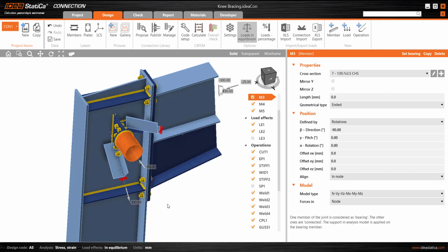There is an invisible link called a super element, which has been introduced in the software to allow a little bit more realistic behavior, perhaps some distortion of hollow sections, some warping of I sections, this sort of thing. But we can effectively consider for the buckling analysis with this model type this end cross section as being fully restrained both laterally and from a moment point of view. So that won't allow a sway buckling mode to show up very easily in the gusset and tongue arrangement.